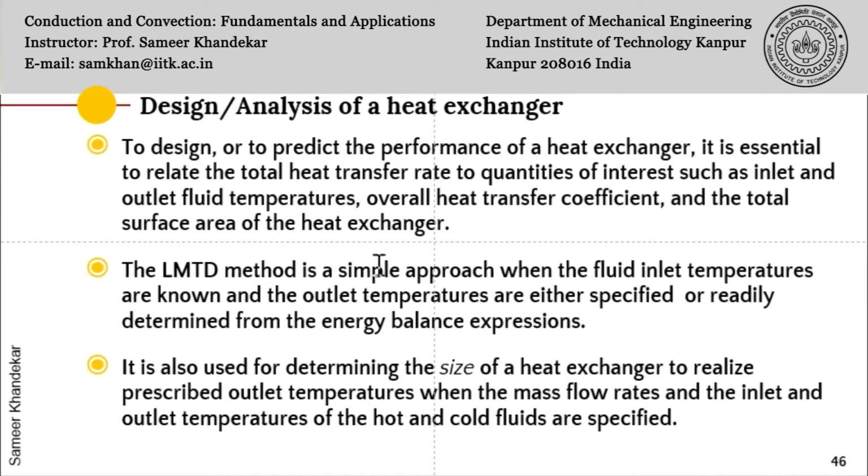For such types of problems, as we said, the LMTD method is a simple approach when the fluid inlet temperatures are known and the outlet temperatures are either specified by the client or readily determined from energy balance expressions.